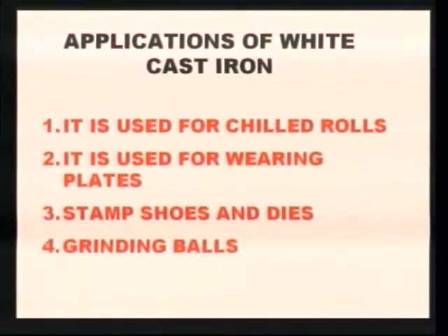Now we will see what are the applications of white cast iron. It is used for chilled rolls. It is also used for wearing plates, and it is used for stamp shoes and dies, and also to make grinding balls.